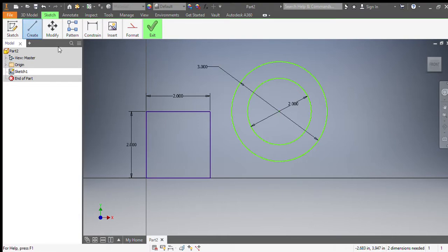Okay, our next tool is an arc tool. With the arc tool, you would select the 2 corners of your arc, and then you would select the top center point of your arc. I am going to type in 1.5, so it is a perfect 1.5 arc.